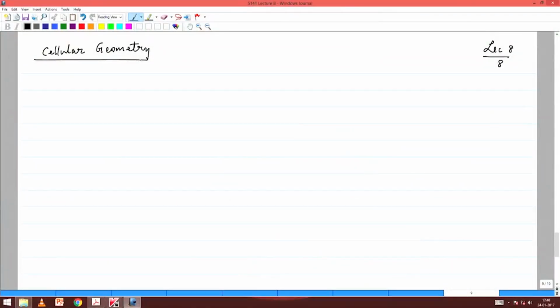What we are trying to understand is, how do we design a system? How do we estimate the C over I? So the aspects are, I want to know the design, so then I can do the frequency planning. The second element that I need to worry about is, what is my C over I? And I'm always worried about that C over I min. I should make sure that I meet this requirement, otherwise I will have an outage scenario.